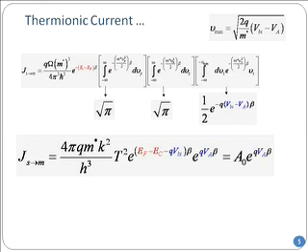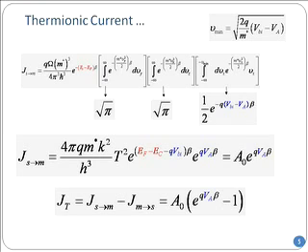Now, that's one thing, that difference between PN junction and a Schottky barrier. There is, of course, you can always calculate the current. Remember that at zero bias, the current from semiconductor to metal must be exactly balanced by the current from metal to semiconductor. So you set VA equal to 0. So the current from metal to semiconductor will simply be A naught. And so the net current is A naught e to the power q VA over kT minus 1.